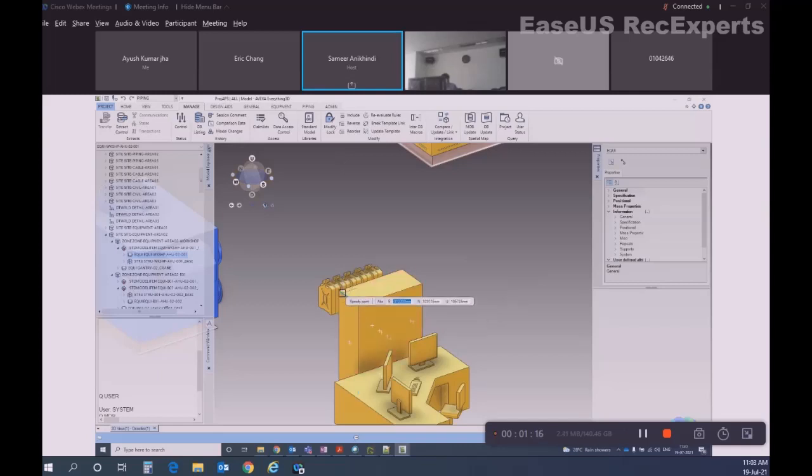Now, if I want to lock this northing, I have to press tab, navigate to the north and press spacebar. So it will lock. So the northing is fixed, right? Northing is already fixed.